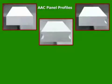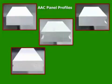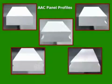This is a vertical load-bearing panel without a profile. This is a vertical load-bearing panel with a half-round profile to add a vertical reinforcement in the center of the wall thickness, in a spacing required by the engineer, which is in accordance with the local requirement. This is a panel with 2 half-round profiles, used when the vertical reinforcement spacing is every 24 inch on center. This is a horizontal panel used mostly for cladding on structural steel or concrete. The last panel is one of our floor panel profiles, which is also available in tongue and groove.